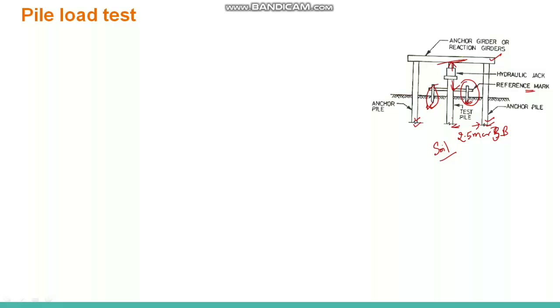Then the test is conducted after a rest period of 3 days. So when we install this setup, after that resting period of 3 days for sandy soil, and 1 month for silt or soft clay.